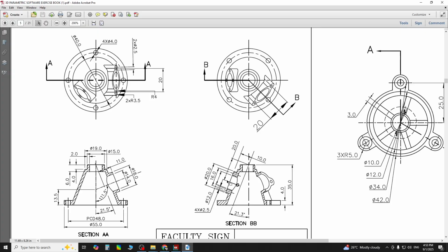Baseline, axis line. So we see the angle also here. This angle we have to also follow. First we will create this 21.3 reference angle line, and then we will take an offset of 10, another line. So 21.3 first we will create, from this point.